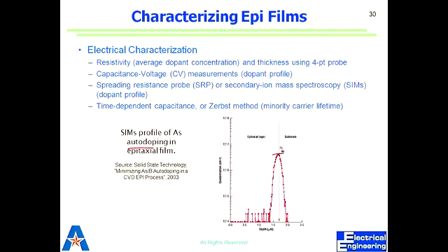So we have a four-point probe. The probes connect to the wafer, the outer two and inner two, right? The outer two apply the bias, and we are measuring current in response to that bias. And current would change depending on the resistivity. Right? We can do that to measure this.